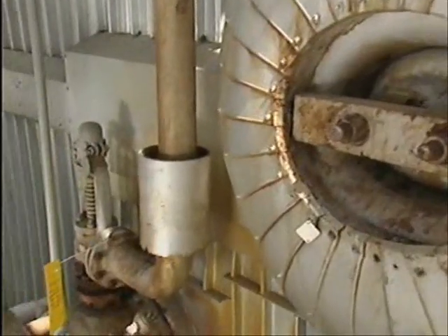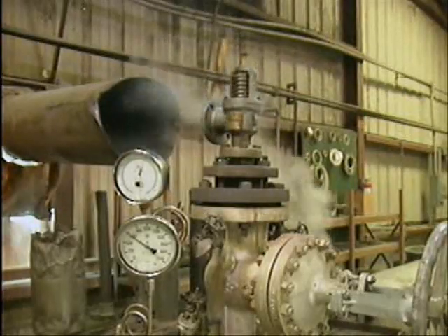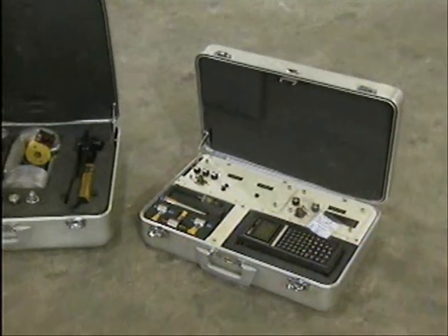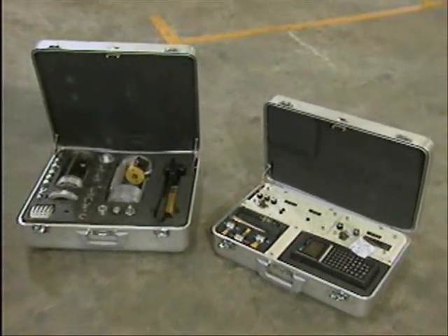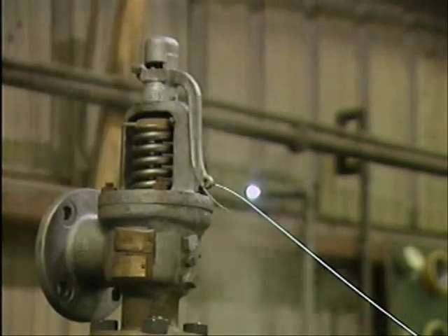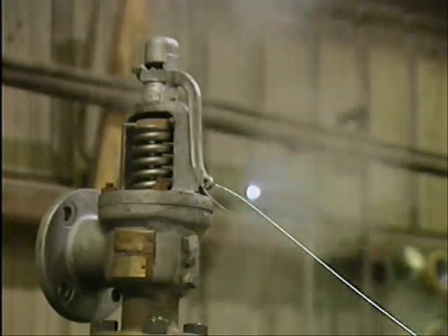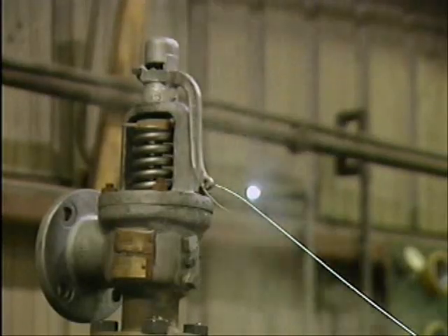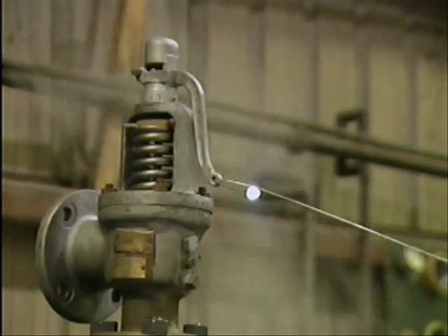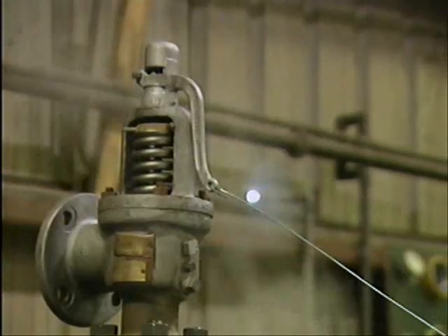Safety valve testing typically includes testing popping pressure. Popping pressure can be tested either by raising system pressure or by using an auxiliary device such as a hydraulic jack to lift the stem. If you use system pressure to test the valve, you should first lift the valve by hand to warm it. This helps ensure that the metal parts of the valve are at the same temperature before you start testing the valve to check its popping pressure.